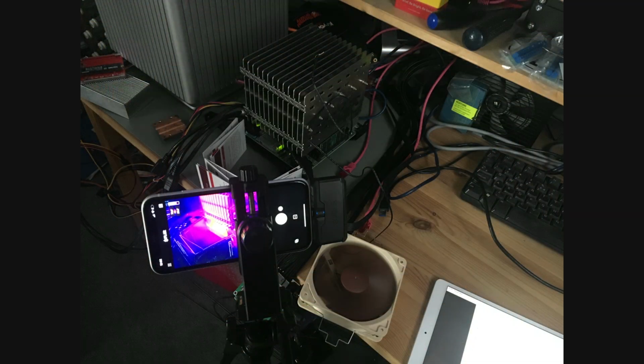In the first part of this video series, I was always talking about the impact of having no airflow. You might have wondered, why am I so concerned about this? If we have a scenario where we use airflow for cooling, we have coolers on top of the devices. Those coolers will have fins, and then there is forced airflow blowing through the fins, which is carrying away the heat. If we have no more airflow, the coolers will just warm up the air around them, and then what happens is what is called natural convection, meaning warm air is ascending by itself, and that movement is what is responsible for carrying away the heat.